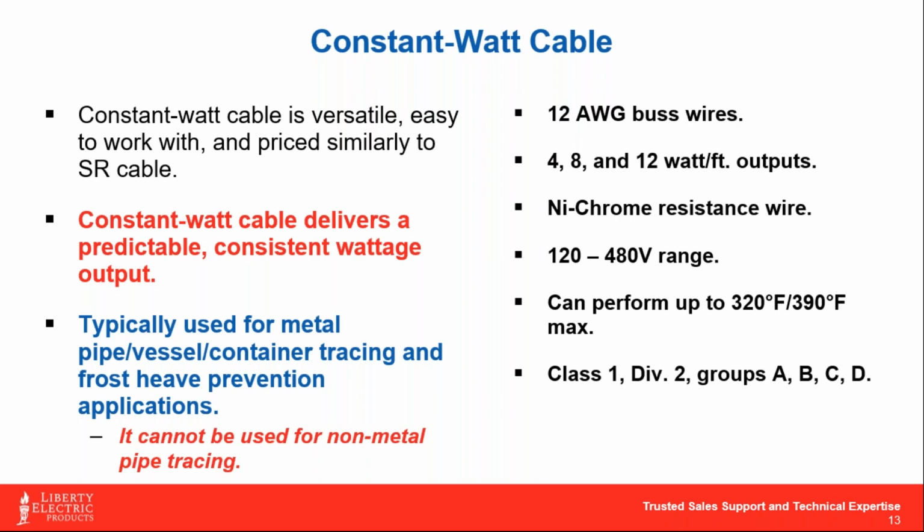This is very easy. If we're using an 8 watt a foot cable, you can simply do 8 times 500 feet divided by your voltage, and there's your amperage draw. Okay, so much easier to figure out your circuits.